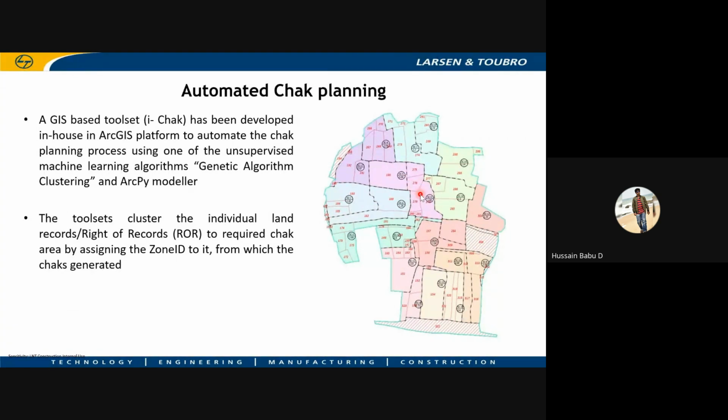This dotted line represents a subcheck, and each color represents a 2 hectare check, between which we will place one outlet point, and collectively 20 subchecks we will call a check. This is how we will divide each and every farmer's land into checks, and we will place OMS for each check throughout the command area.